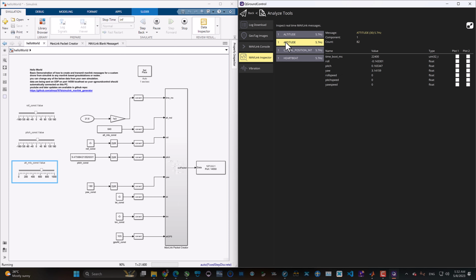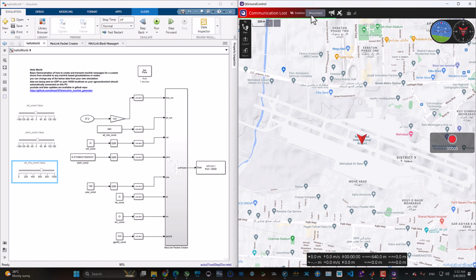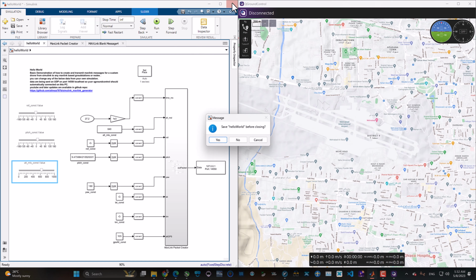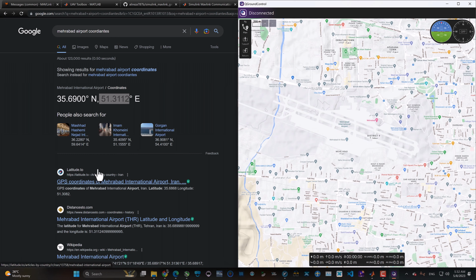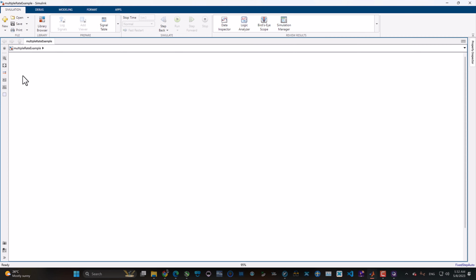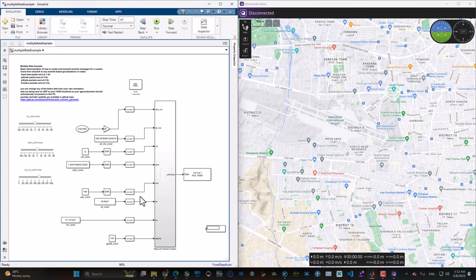We don't want to send the heartbeat at 5 Hz. We want to send the attitude at maybe 5, 10, or maybe 100 Hz, but the heartbeat at 1 Hz. So in the next step, we're going to use the other file, which is multiple rate transition, and try to send data in a more real fashion. We want to send them with different rates. This is almost the same example that you had before, but with some consideration for the variable rate of transmission.